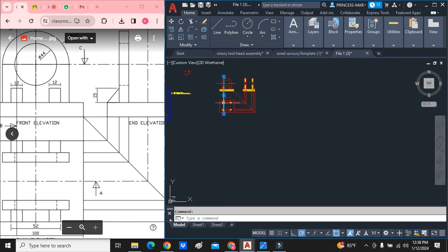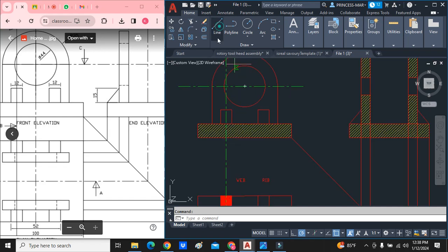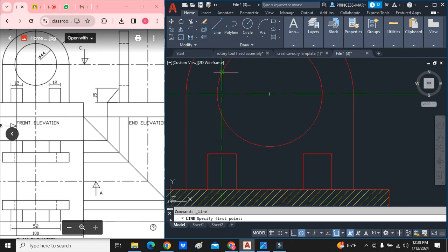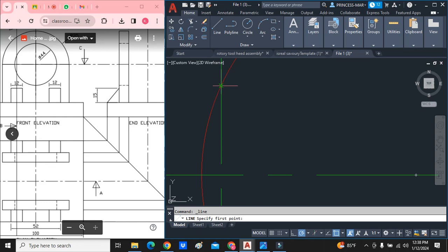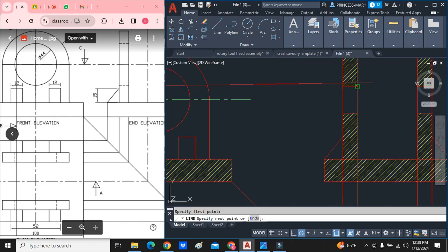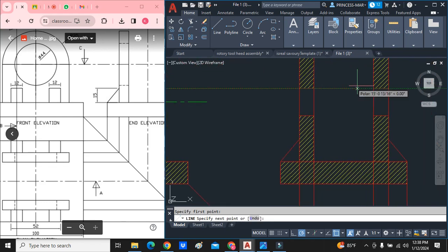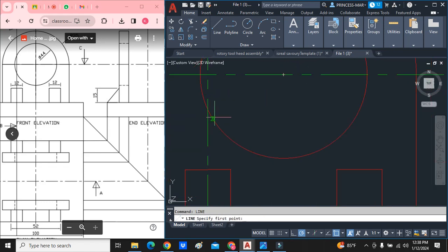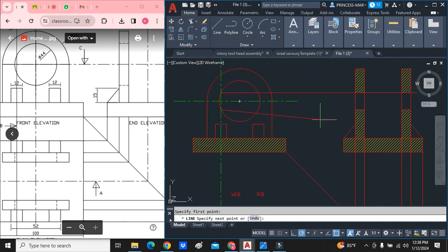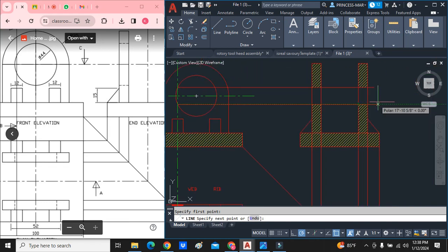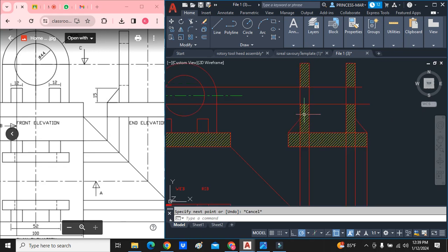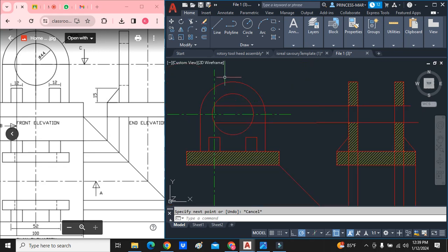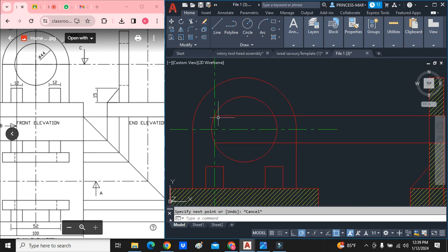So when we look at it, Aaron did a very smart thing here because he saw where the line cut the piece and he projected it across. Yeah, this is high level here, Aaron. Very good. So he projected where the line cut, over there the top, over there the bottom. So this is correct. The cutting plane cuts through this piece and it cuts here, it cuts here.